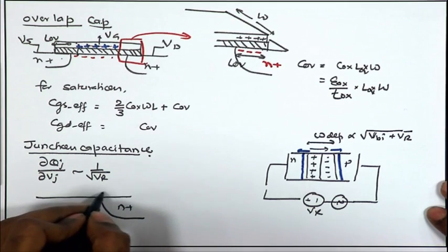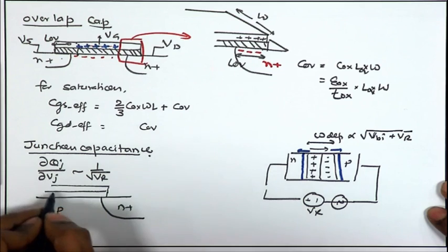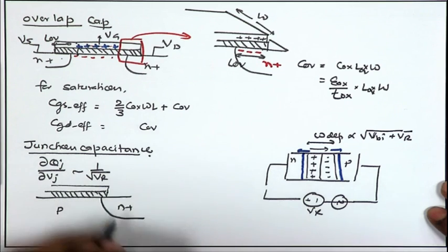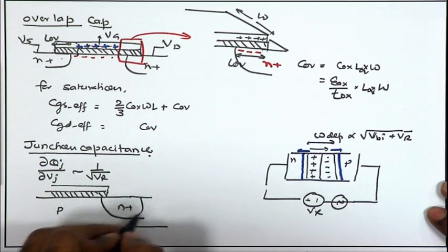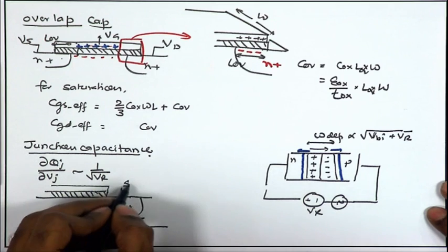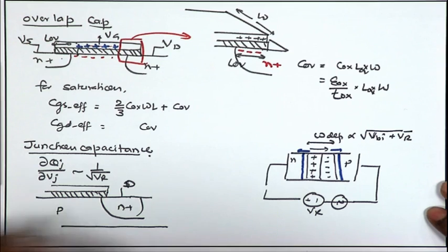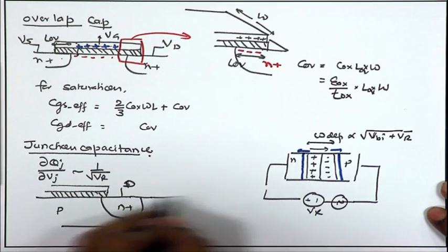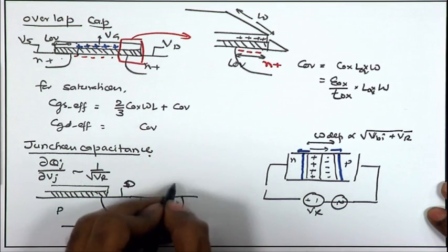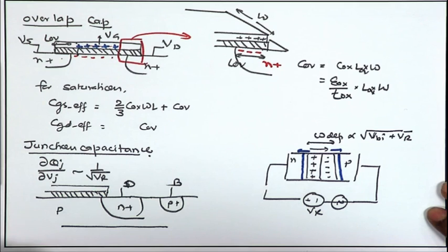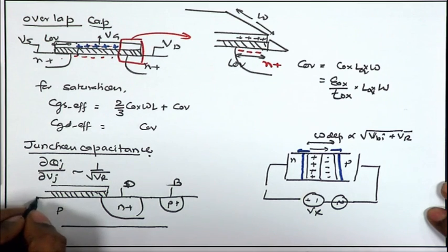whenever we are changing the overall potential between the source, say let us call it drain, and the substrate. So, for the substrate potential, we have seen that it needs another contact. So, you can assume there is a P plus contact for the substrate. So, this is the body terminal as we have seen. I am not drawing the source part, let me draw that also. N plus is the source.